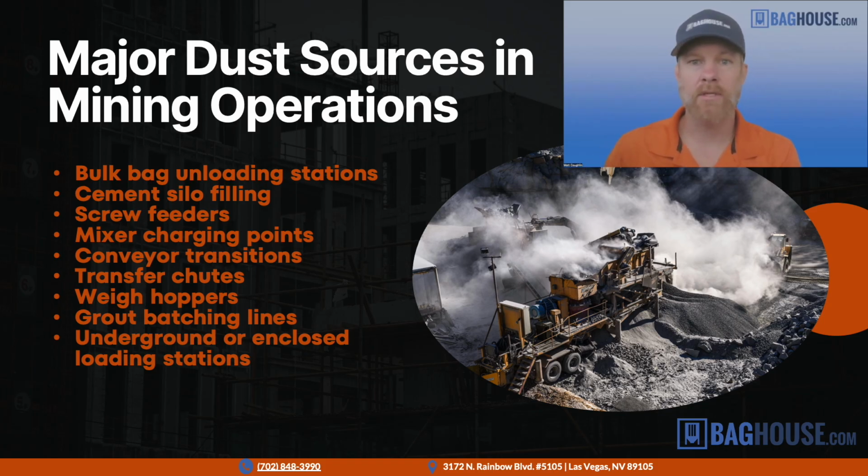Again, major dust sources in mining operations. Look at your operation. Where are you seeing the dust? And again, it's going to be material handling, transfer points, bag unloading, silo filling, where you're using screw feeders, conveyor transitions, transfer chutes, weigh hoppers, batching lines, enclosed loading stations. All of these are potential dust sources, and they all require some special attention.